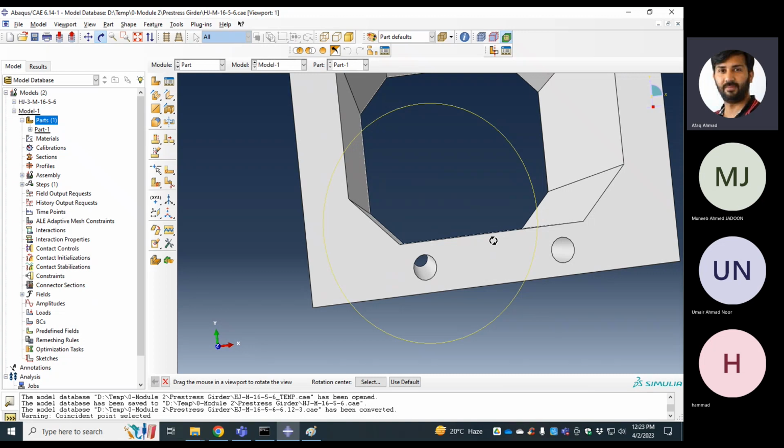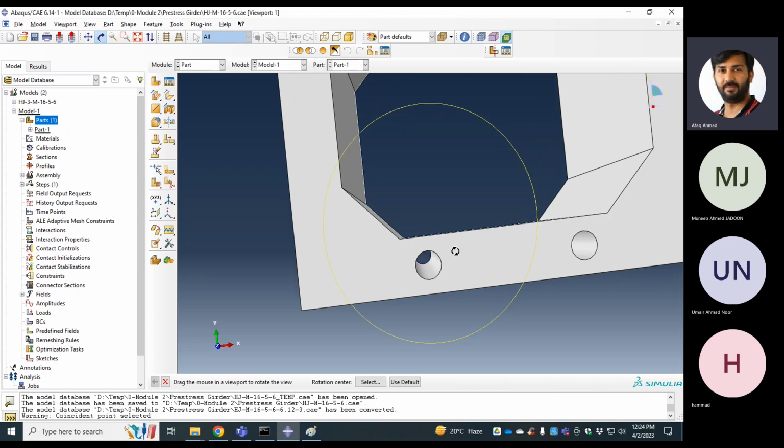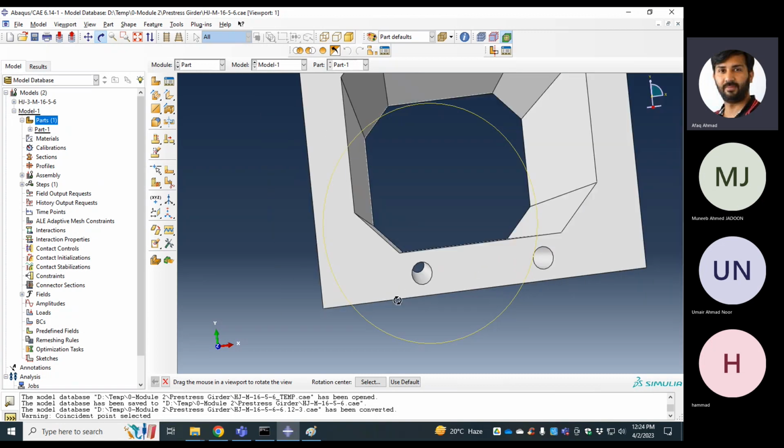Then we do the concreting, and then we apply the pre-stressing on the structure. So if you're studying this behavior, then you need these small ducts inside the concrete member, and you will insert tendons inside them, and you are going to investigate the stresses applied on the pre-stress tendons and towards the concrete, and how the concrete behaves around these tendons.